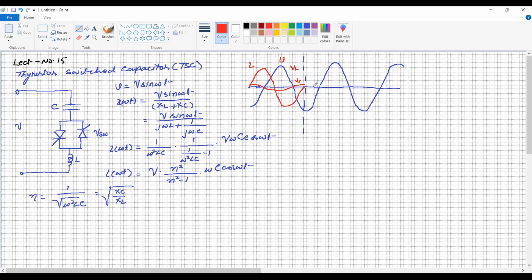Okay, so now when the current becomes 0, the voltage across the capacitor is equal to the system voltage, and this is called the charged voltage across the capacitor, or the capacitor is charged even if the supply is disconnected. Now this voltage VC plays a very important role in switching on and switching off the capacitor. How is it?